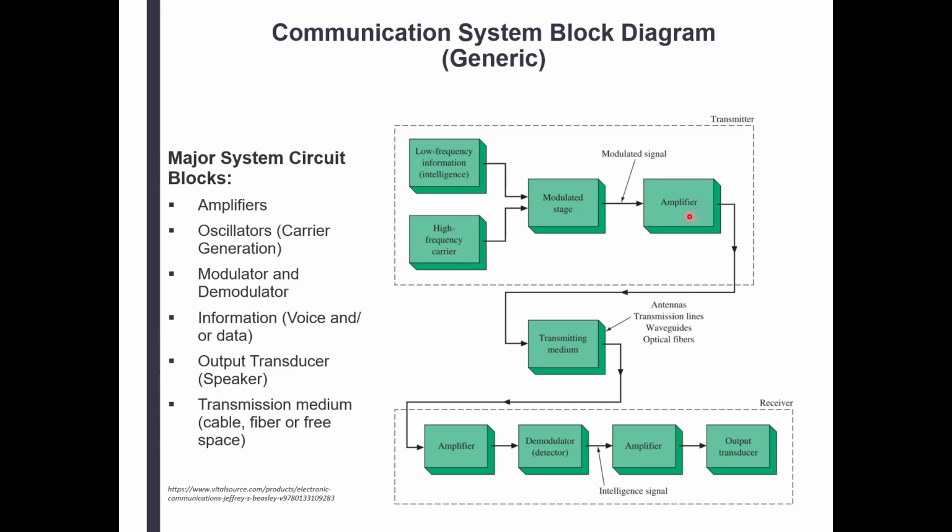So that modulated signal is being carried, or the modulated carrier, the carrier that's modulated by the intelligence, is combined, or the technical term is mixed. That's the mixing stage, because the low frequency intelligence is mixed with the high frequency carrier. Now that modulated carrier is being carried through whatever medium that is, fiber, copper, or air, and then is being picked up by whatever receiving stage.